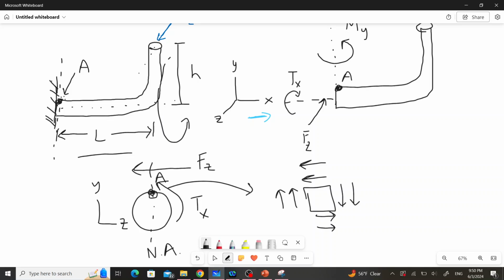And then kind of like the last problem, there's a bending stress, but since the bending is about y and we're on the neutral axis for y, we know that there will actually be zero bending stress caused by that moment at this location A anyways, right? Because A is right along the neutral axis, so there won't be any tensile or compressive bending stress along A from bending. So we're going to omit the axial stresses altogether here.